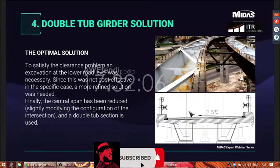This solution has a high cost and weight, but gives the possibility to reduce the height of the deck package. Furthermore, to respect the available clearance requirement, we need to slightly modify the configuration of the intersection, achieving a reduction of the central span to 40 meters length.